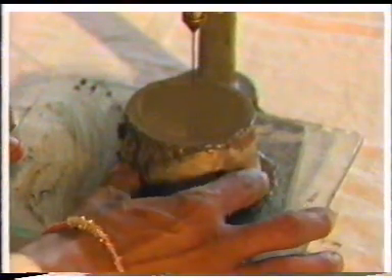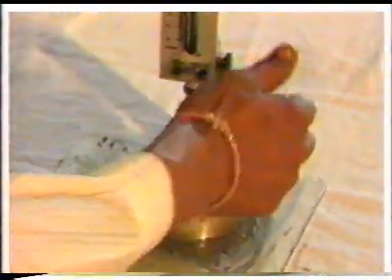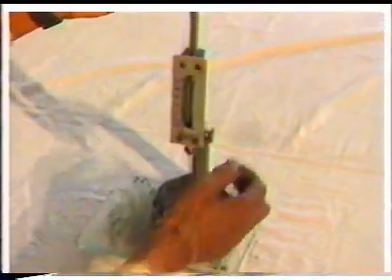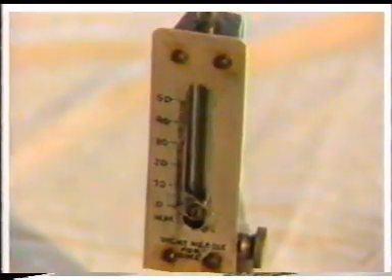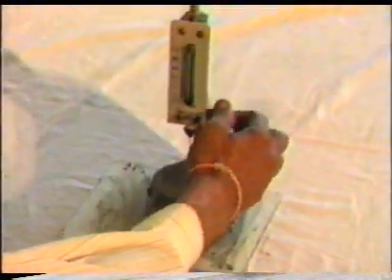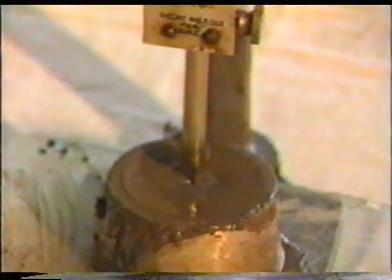Lower the needle till it comes in contact with the surface of the test block and gently release, allowing it to penetrate into the test block and observe penetration. Repeat this step at appropriate time till the needle fails to pierce the test block 5 to 7 millimeters from the bottom of the mold, and note this time.